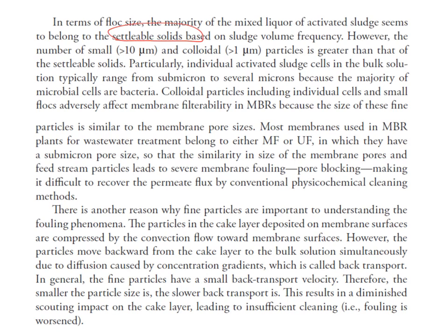However, if you look at the impact of the particles on the membrane performance, small particles are more important, and you can imagine from the Carman-Kozeny equation, which shows that if the particle size is smaller, the cake layer has lower permeability, which means the same amount of particles can form a more impermeable cake layer. So the number of small particles is more important.